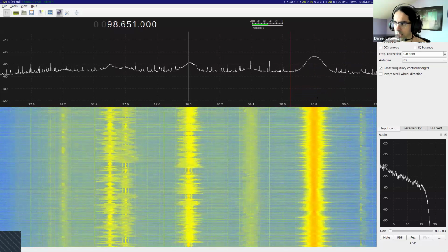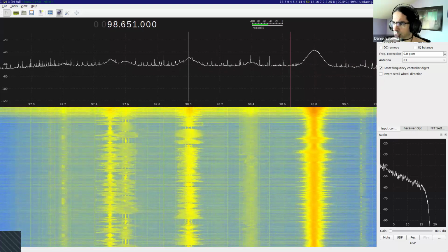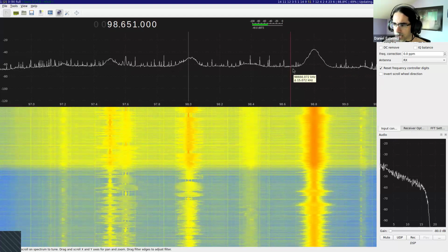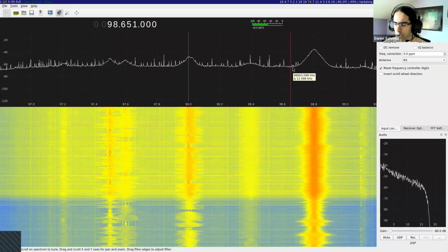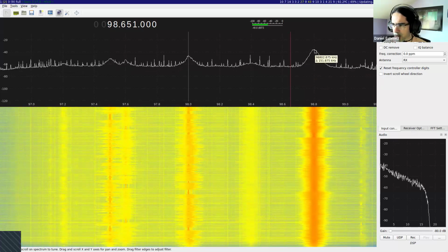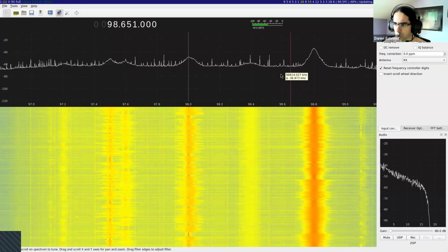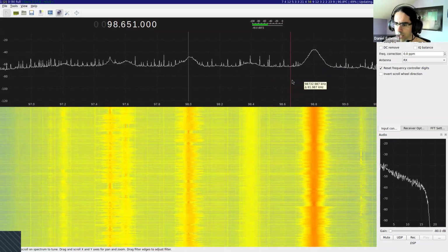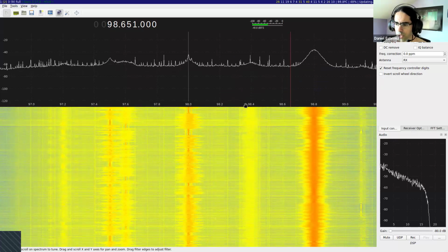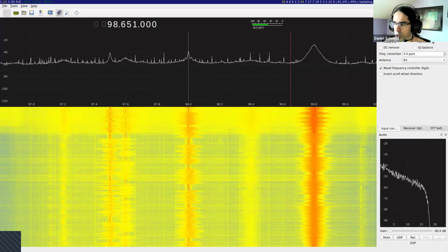And in this case, it's the same. You can do the math, but I think it's the same. We can increase 10 dB more. And now we can see that the noise has increased by more than 10 dB. And actually, if you look at this, it's maybe only 30 dB of signal to noise ratio because the noise has increased more than the 10 dB increase I did. And the reason for that is that the gain is too high and the receiver is beginning to saturate. And if I keep increasing this, then we get a worse and worse scenario.